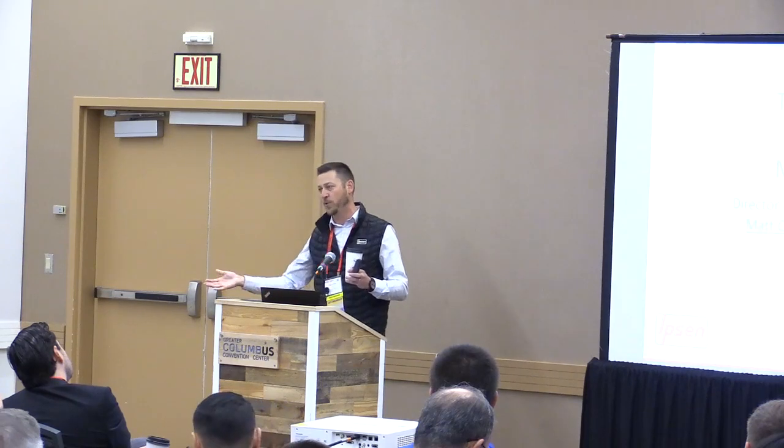And you don't have to do it through just strictly human interface, right? You can let the machine decide that. You can say, I'm comfortable advancing to my critical soak once I get to plus or minus 25 on my final step. And then your final soak, you would set up and say, I need that thermocouple in that biggest part because I've got mixed tools now. I need that thermocouple to be in range before I start the timer on my austenitizing, assuming you're doing a hardening cycle or whatever you're doing. So that's the way that you would do that.